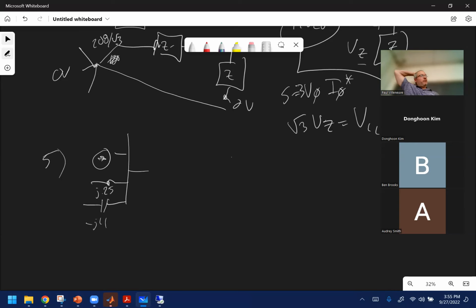An inductor, when you model it as an impedance, does it have a positive J or a negative J when its units are ohms? An inductor. Yeah. So these were all in ohms or per unit ohms, correct? Because J.25 has definitely not been inverted. So all you had to do was invert all those. And some people tried to put them in parallel and all that stuff. You didn't need to do that. That's the beauty of Y bus. They're all just connected to a bus. As long as they're not in series, you literally just start adding up.